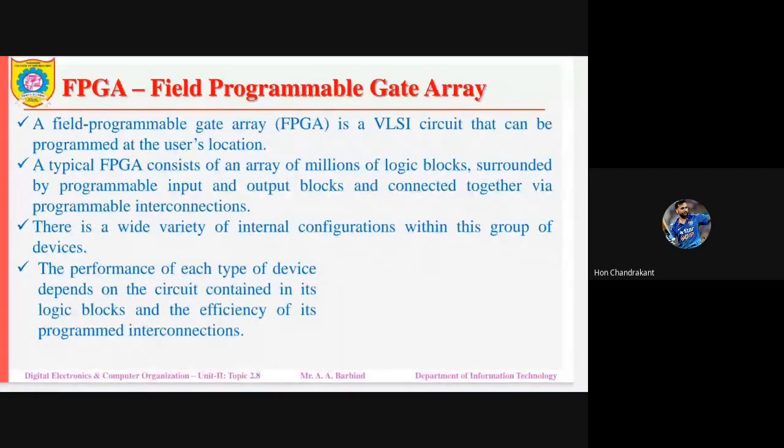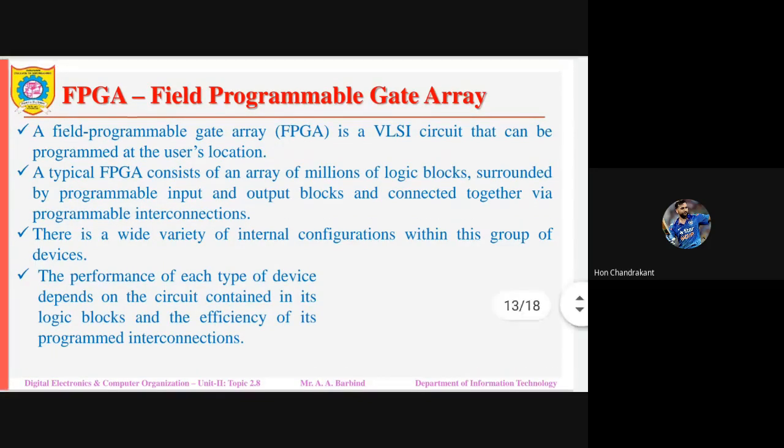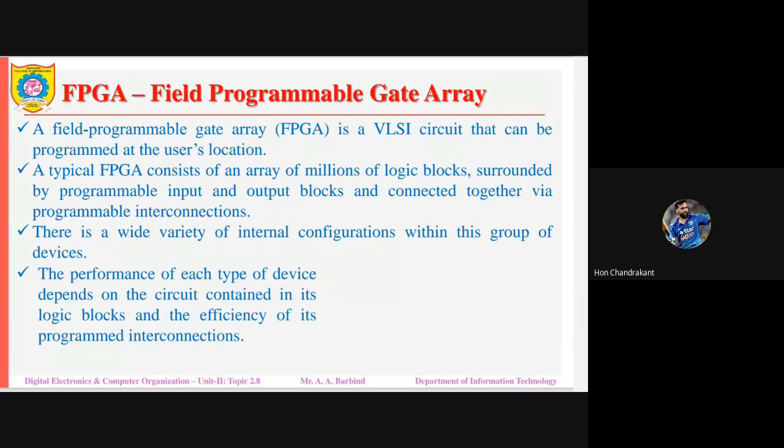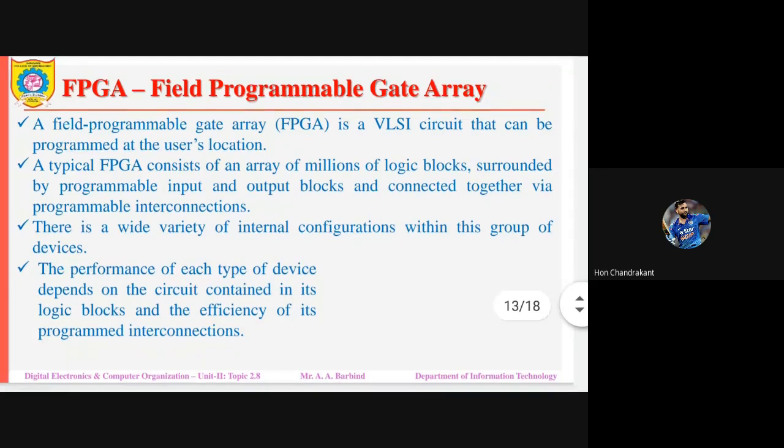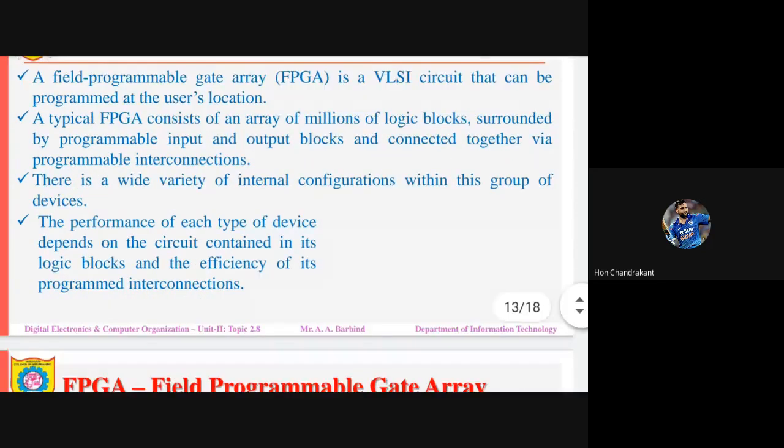FPGA is a field programmable gate array. This field programmable gate array is a VLSI circuit, VLSI in the sense of very large scale integration circuit. That means there are many devices inside this FPGA. It is even more complex than a CPLD. A typical FPGA consists of an array of millions of logic blocks surrounded by programmable input and output blocks and connected together via programmable interconnections.